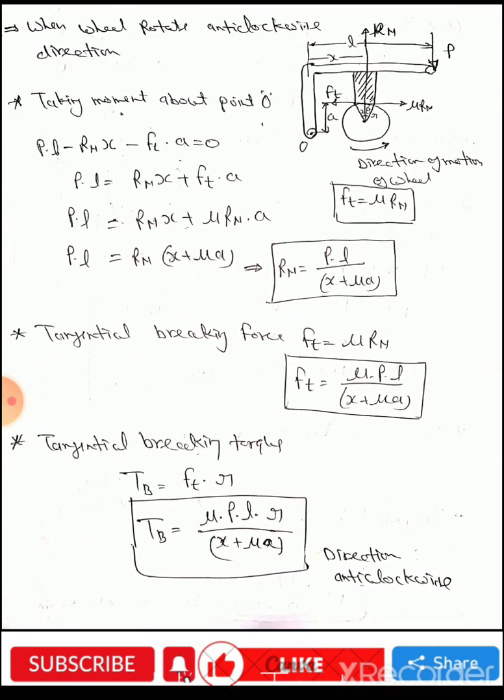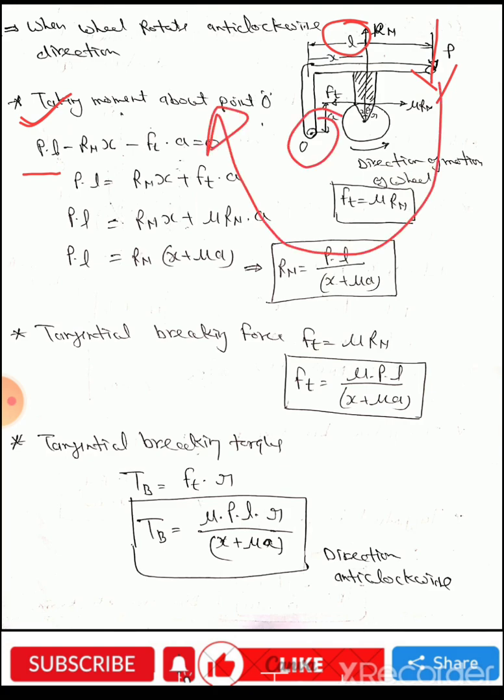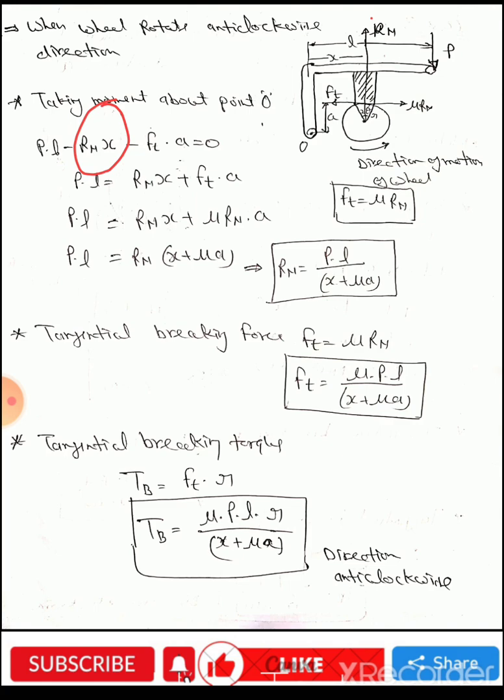Now come back. Taking moment about the fulcrum point O. PL is a positive couple, P being the downward force into perpendicular length, making a clockwise couple about point O. Next couple Rn into X is in negative sense because Rn is the upward normal reaction with perpendicular length X, making an anti-clockwise couple about point O. Next couple Ft into A is also in negative sense because Ft is a left side force and its perpendicular distance A about point O makes an anti-clockwise couple.